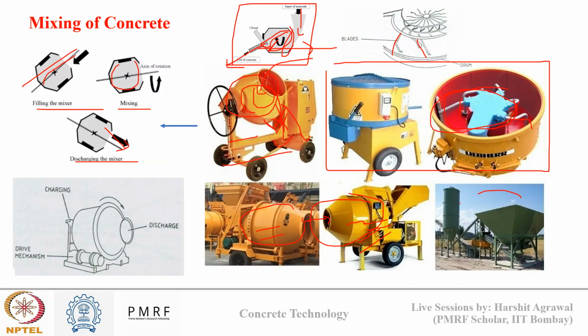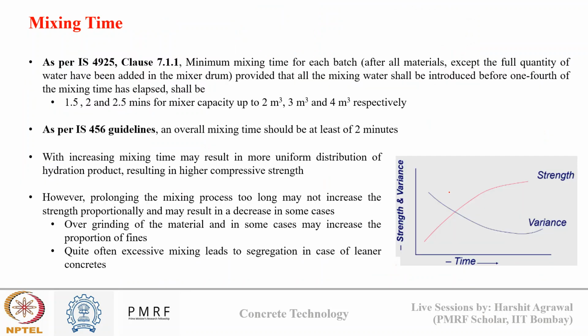Okay, and in this last image you can see a continuous mixer. As the name suggests, here the loading, mixing, and unloading is done continuously until the job is complete, and that's why it is used for large scale projects like dams, bridges, and high rise buildings.